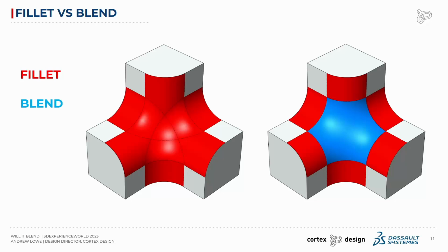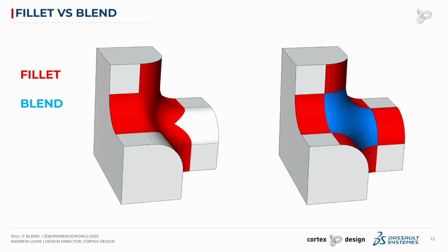So when we're referring to these kind of fillets versus blends, fillets are typically what the fillet tool gives us, with exceptions, and blends are geometry that we've had to go in and manually create ourselves to be able to get either the functional or aesthetic requirements of our parts. And if we look at this example rotated a little bit, you're going to see that the only fillet-based transition almost has a pucker into the part. I don't think anyone would intend that to be the intended geometry, and the blend brings the geometry to where it needs to be.